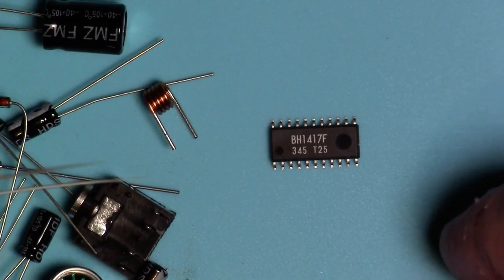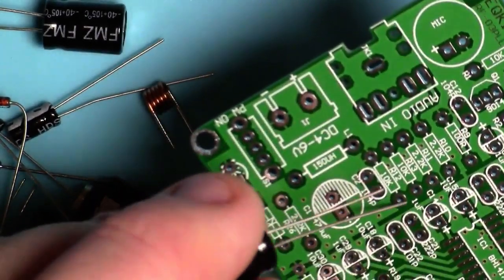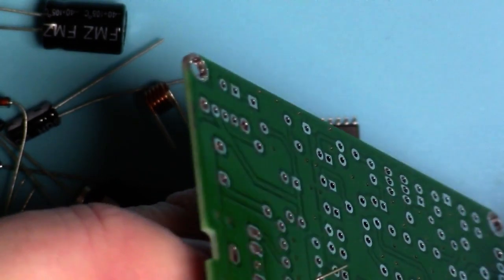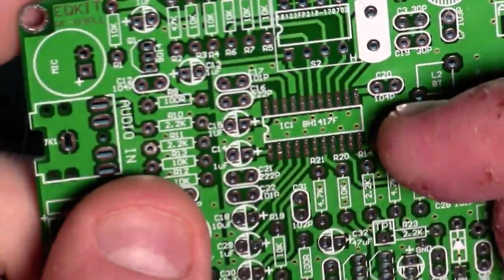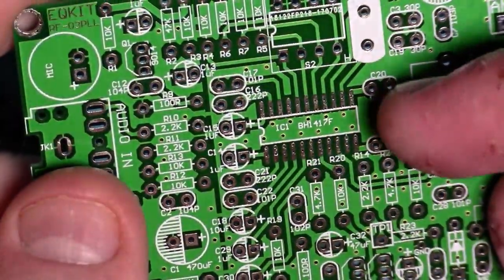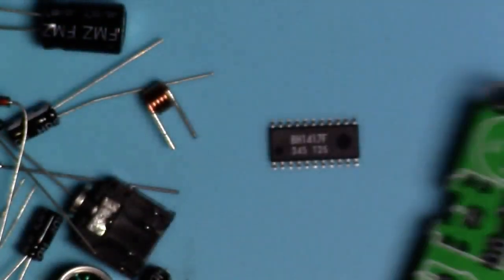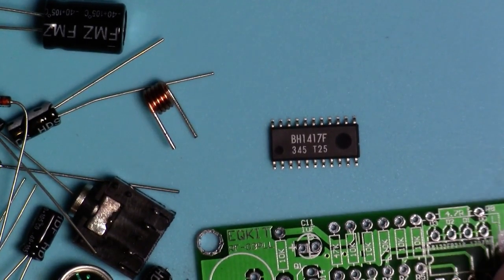You see all these other devices have long leads on them, and these leads actually poke through the holes in the circuit board, like that. But an SMD part is going to be soldered directly to the board, and these are quite a bit more difficult to solder, typically. And the kit wants us to start with that.